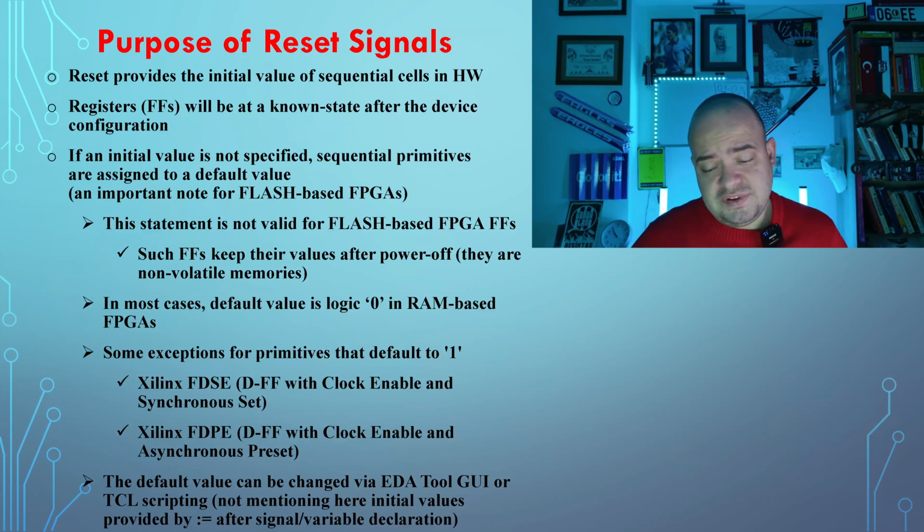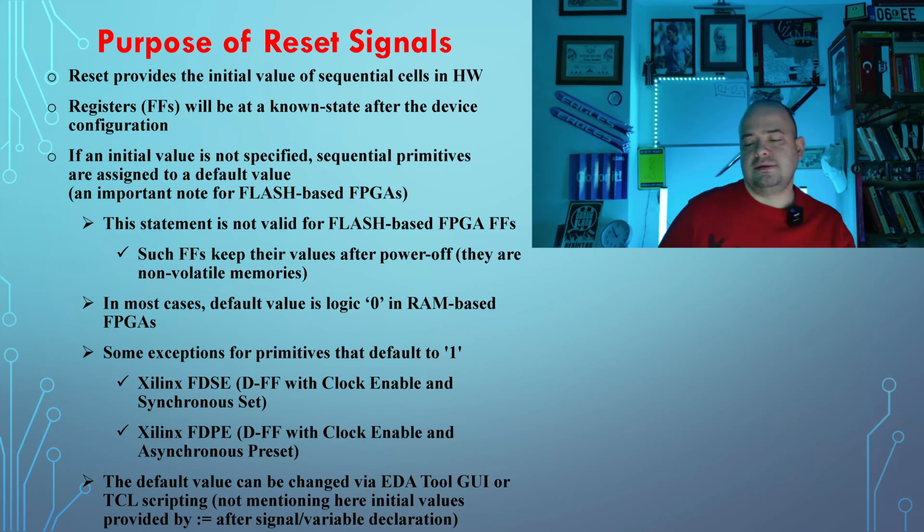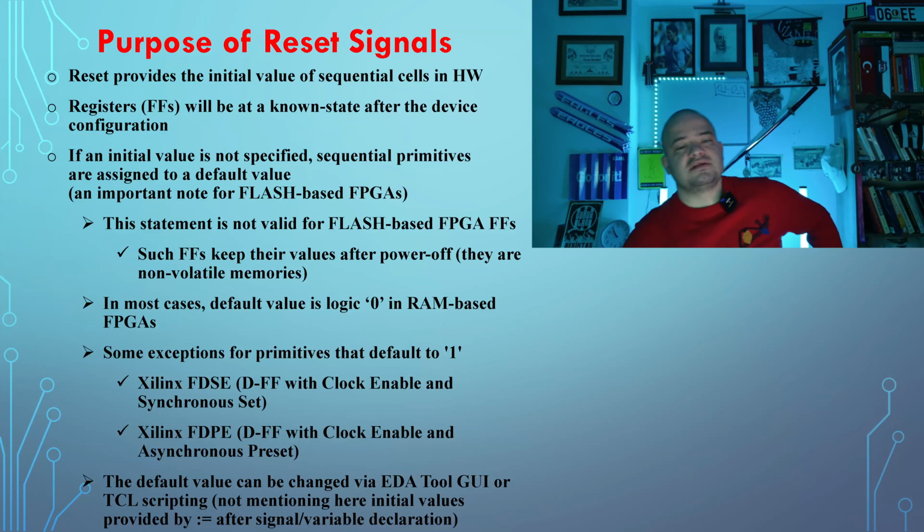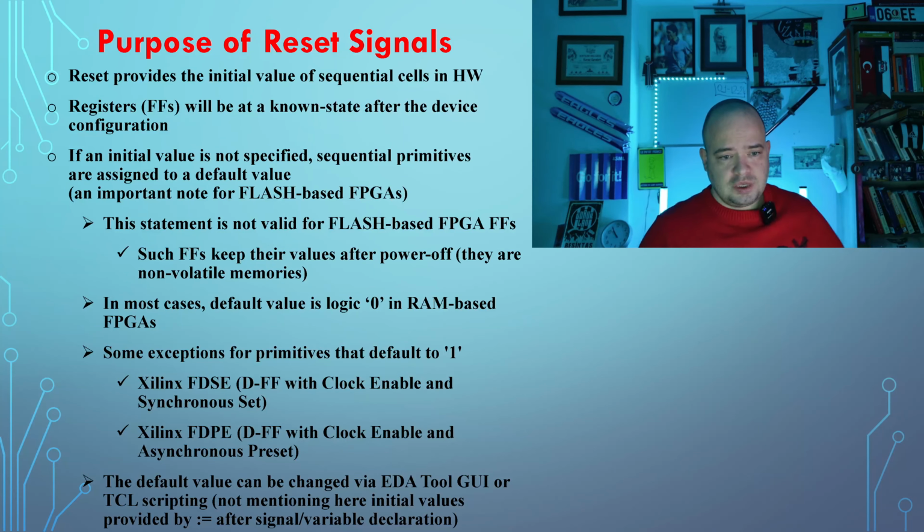And if it is an asynchronous reset, then you need to have that asynchronous assertion, synchronous deassertion behavior properly. Then, instead of saying setup and hold, since an asynchronous reset is an asynchronous control signal, the terminology is recovery and removal time, because they are asynchronous inputs.